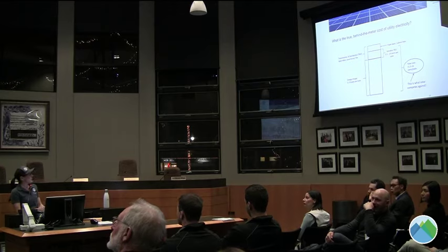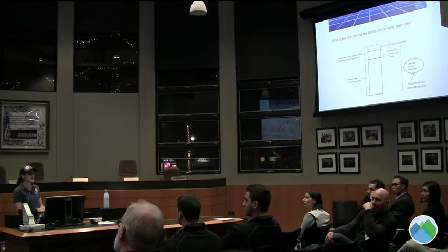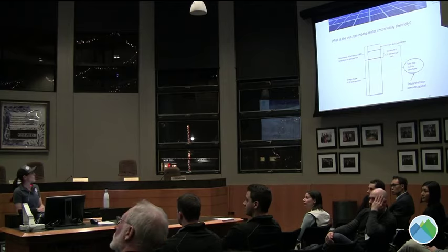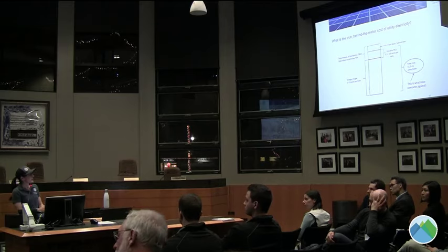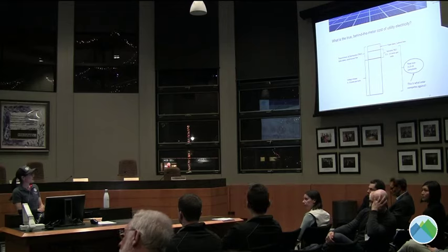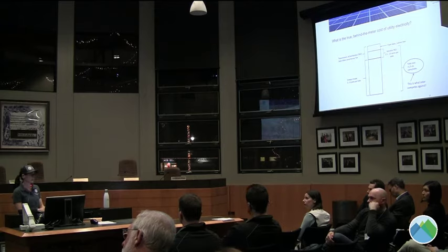The second portion is the variable transmission and distribution, and that is going to vary between 5.5 to 10 cents per kilowatt hour. That's going to be based on how many kilowatt hours you draw from the grid. And then you have your energy charge at the bottom, somewhere right now between 6 and 8 cents per kilowatt hour. So the total cost over on the right for all of that is 11.5 to 16 cents per kilowatt hour. And that's what we have to compete against.